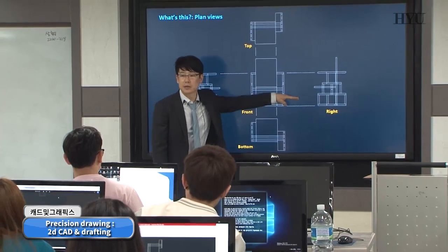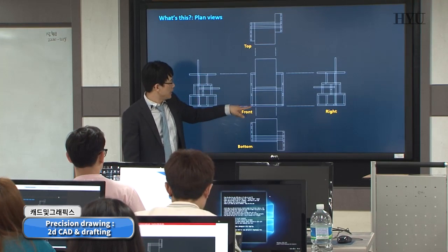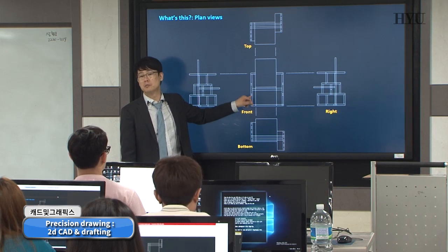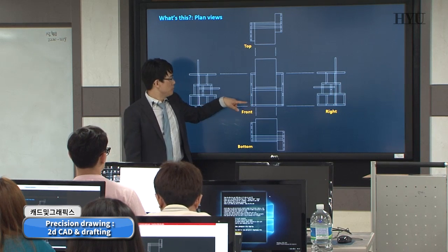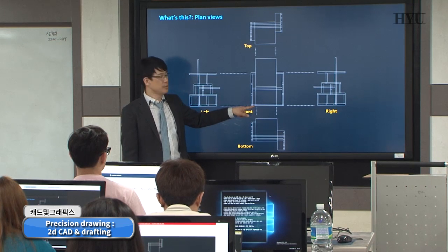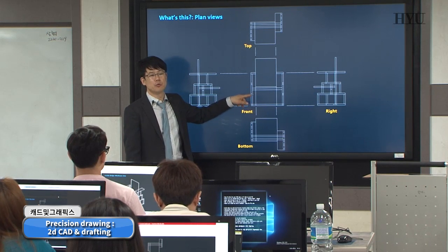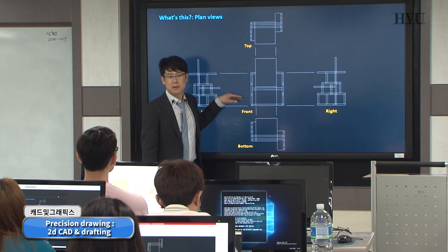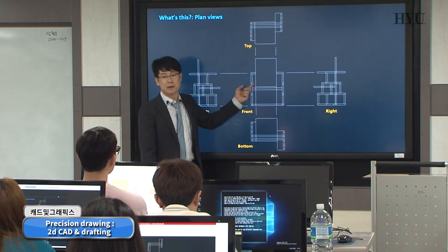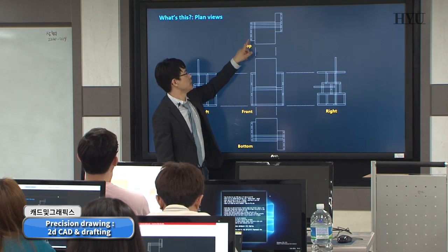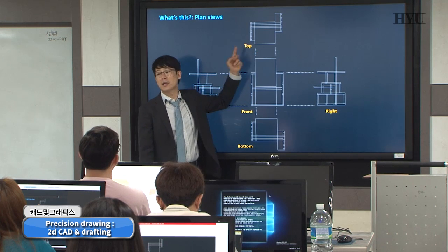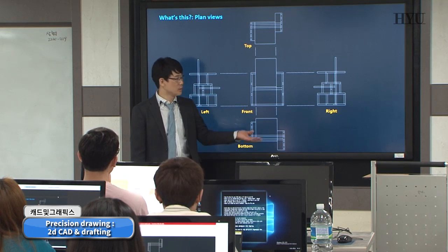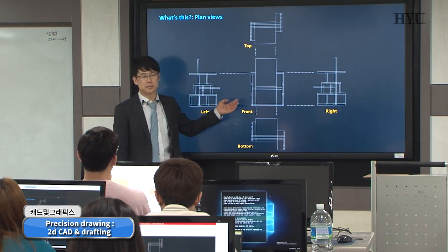It's a section cut, where the height is around 1.2 or 1.5 meters from the bottom. The section profile at that elevation is going to be the floor plan. That is the conventional definition of the floor plan.